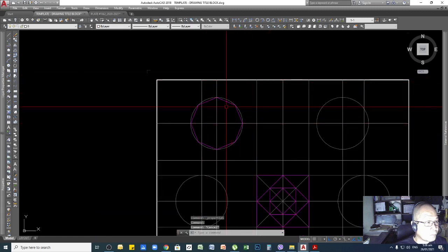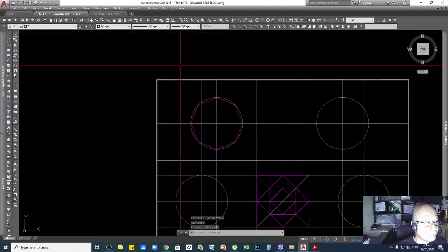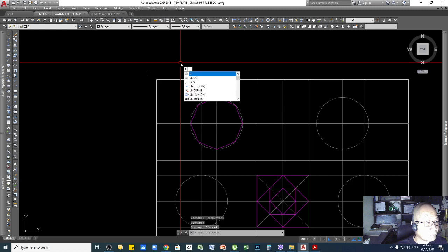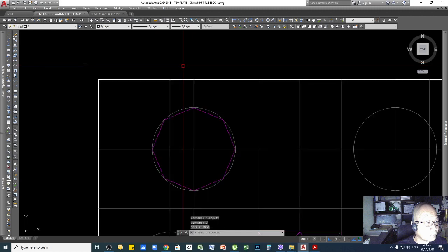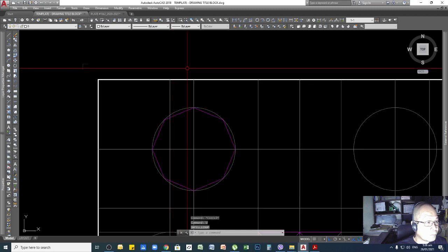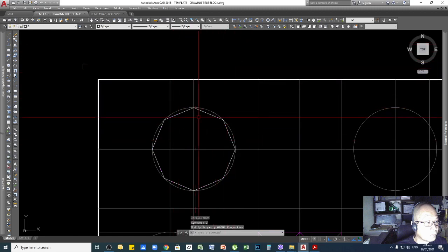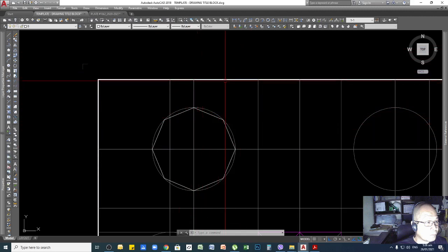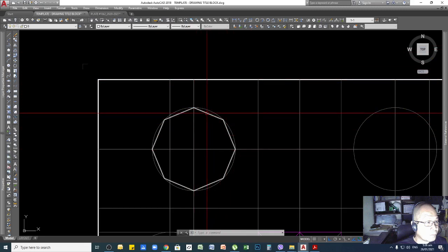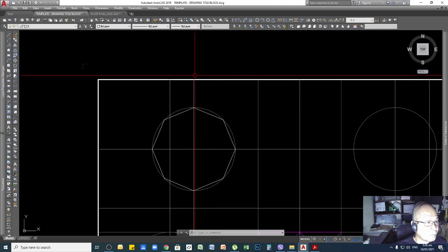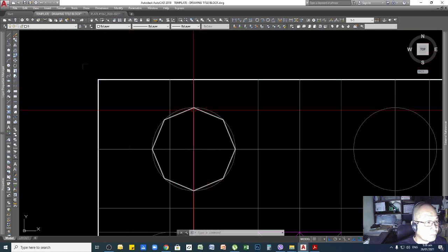So that's one way. The other one, okay, I will undo. Just type U to undo, enter, undo again, because I moved the drawing on the screen. The first undo was to bring back the view, and the second undo was to bring this back to its original property. What I demonstrated is changing the properties of this into magenta color.